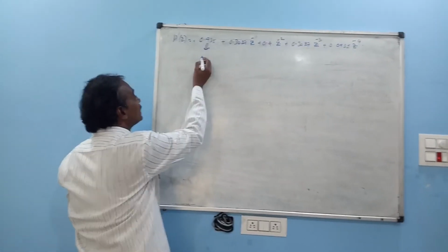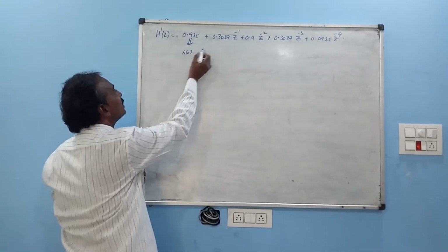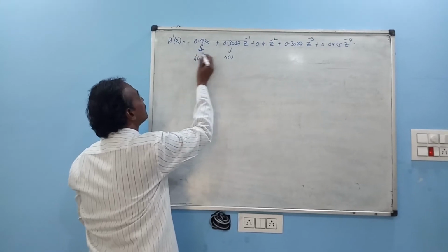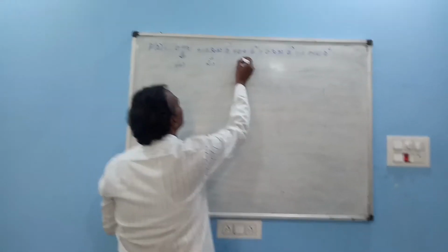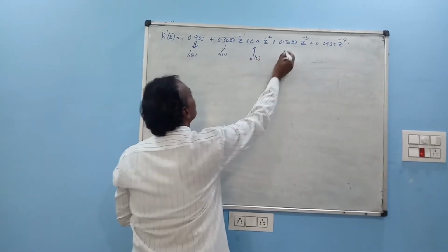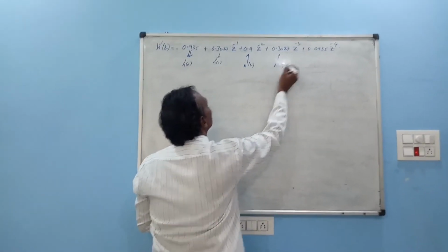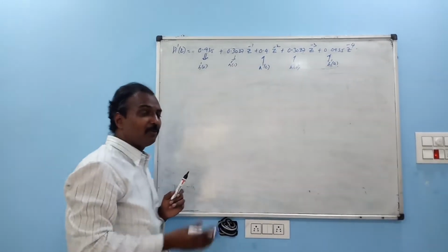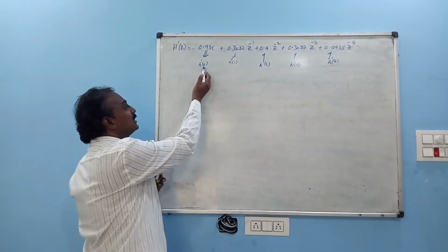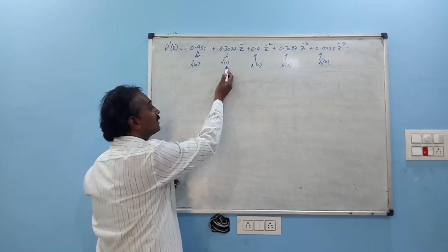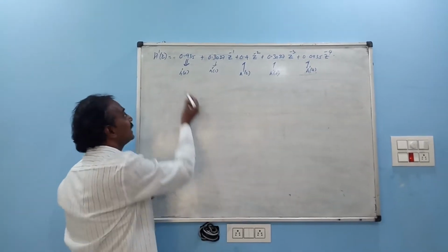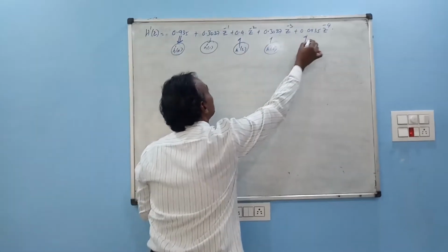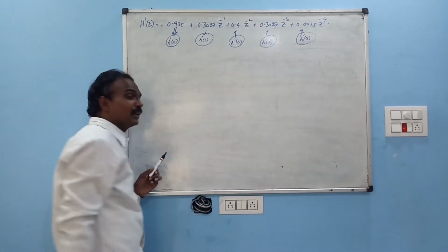So the new coefficients are h dash of 0, h dash of 1, h dash of 2, h dash of 3, h dash of 4. Because earlier whatever we had from minus 2 is shifted to 0, minus 1 is shifted to 1, like this. Dash represents the new shifted coefficients. I am shifting to the right side to get a causal sequence.